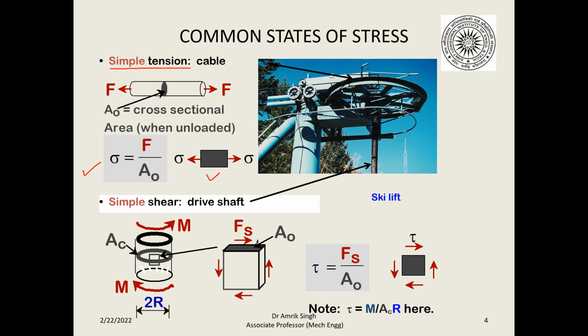So it is complementary. So this is a stress on these opposite faces, and you see this will try to develop a couple which is clockwise, and this force which is complementary shear force, it will try to develop a couple which is anti-clockwise. So if they are of the equal distance.